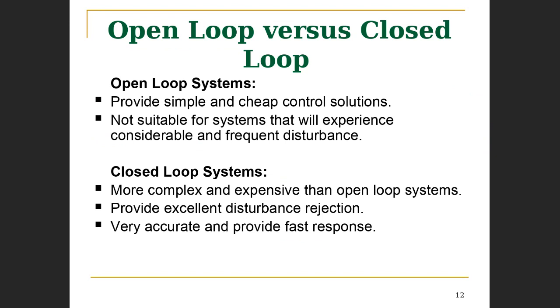Now, let us compare these two systems. For open loop systems, we see that these systems are very simple. And because they're simple, they're typically cheaper than closed loop solutions, right? So they provide a simple and cheap control solution. However, open loop systems are not suitable for systems that will experience considerable and frequent disturbance.